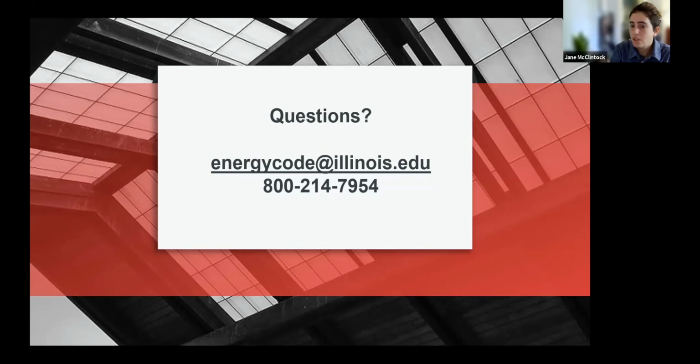And questions, we have one question that has come in about vaulted ceilings. So if you've got a home that has a standard attic, but you've got a dormer with a vaulted ceiling extended off of that, those would be entered as two separate assemblies in the Manual J. You would have the standard attic and the ceiling partition between that standard attic, and then the dormer would be a separate ceiling entry in the Manual J. So you would enter both of those, and it would be considered a vaulted ceiling entry.